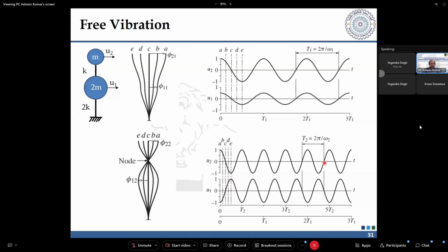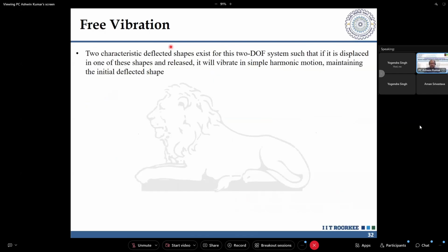And the final thing that I want to say is, the mode shape is a non-dimensional quantity. It is just a representation of the fact that if I have a natural frequency, it has a particular mode shape associated with it. If the shake table is agitating the table at a particular frequency, let's say for the multi-degree of freedom system, 4 hertz was the location which corresponded to the first natural frequency, the system is going to respond in this way itself, harmonic, and it will show the same phase of movement that we saw in the video. I hope it is clear as per my explanation.